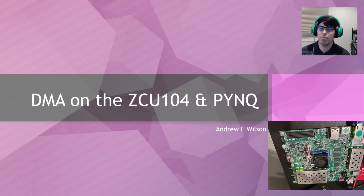We're going to be talking about DMA on the ZCU and the PYNQ. So this is a continuation from yesterday, where we ended short because the bit file took a long time. Because they are using proprietary HDMI PHY and transceiver receivers, my bit file actually didn't finish. I need to get the license for that to get it to work. So I went ahead and just did a quick DMA version so we can go through it.